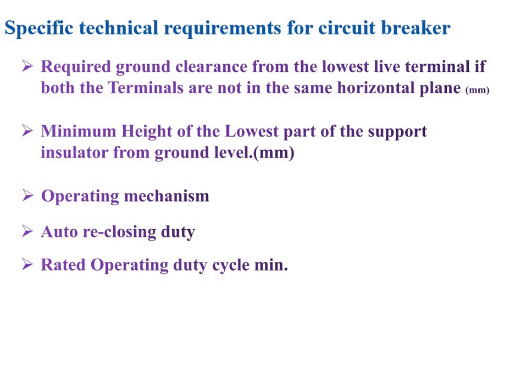Then again close, then open, then again you have to wait for some time, and this is generally 3 minutes. You have to wait 3 minutes and then you can go for the close. So depending on the type of fault, if that temporary fault is not cleared in 0.3 seconds, we can again wait for 3 minutes and then we can go for the closing of the circuit breaker contacts. So that rated operating duty cycle you have to mention.